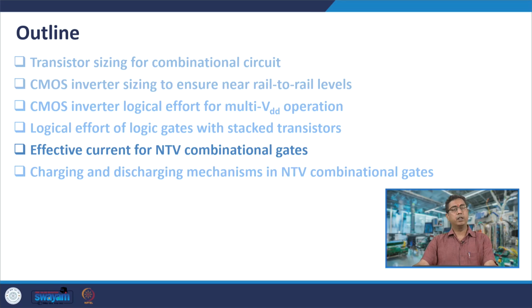Welcome to this lecture. This is in module 2, and this lecture is on the effective current model for NTV combinational gates. Today we will discuss the effective current of near threshold voltage combinational logic gates, especially NAND gates. The same would be valid for NOR gates, with a similar approach. As a part of this, we will also discuss the charging and discharging mechanisms of NTV combinational gates.